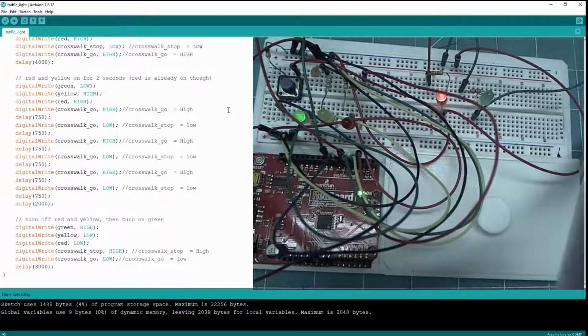And what we want to do is, we want to immediately go to the red light as soon as it goes to the green light. So let's look at that spot. And what it is, we've got a delay right in here. After that blinking light, let's remark it out. Let's upload it, and you'll see that delay going away. It'll go directly from a flashing green to a red and a green light on the traffic light.